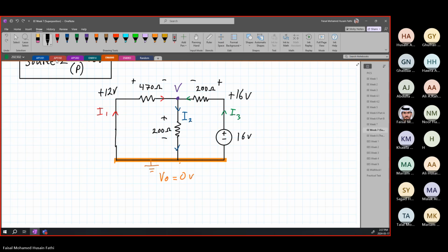This circuit is shorted. Again, current directions are all going to change once more, depending on the new circuit, and we have only one voltage source now. Same exact method again. So 16 volts, we know it's going upwards, so the current has to leave from the positive side. The direction of this one, let's call it IP3, is going upwards.